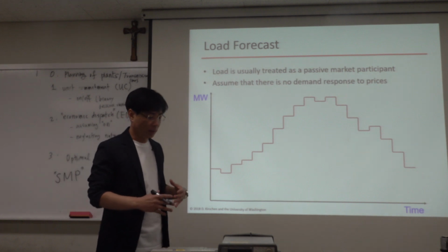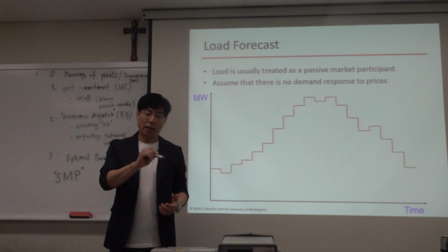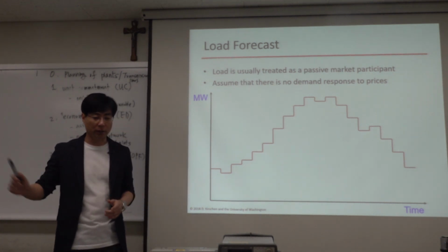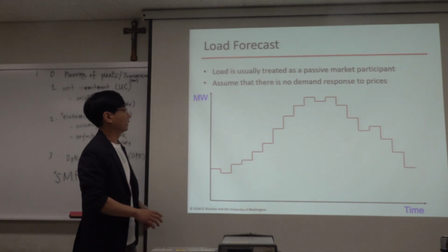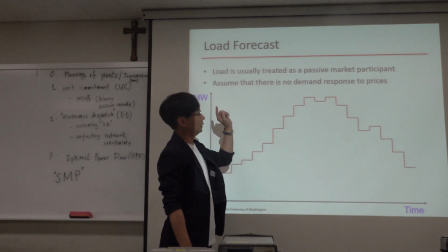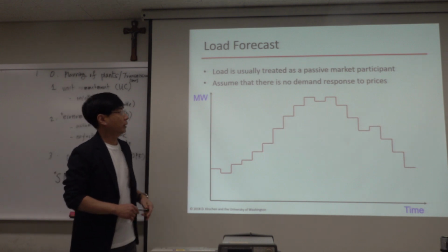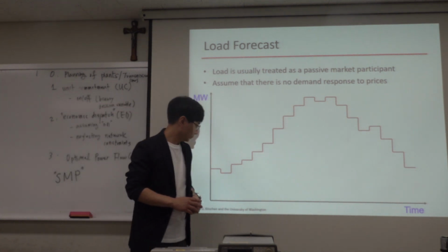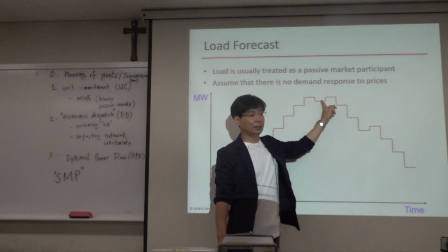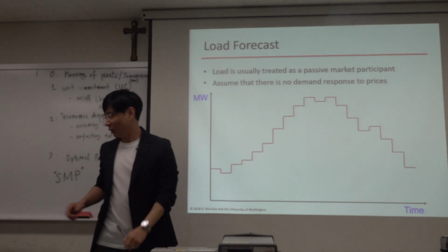Anyway, generator bids, and because the customers do not directly participate in this market, the ISO does that job instead of the customers. So they do forecasting. This is load forecasting. And load is usually treated as a passive market participant. Here we assume that there is no demand response. So load changes, what is it? Lunchtime. Lunchtime is coming. We are all hungry.